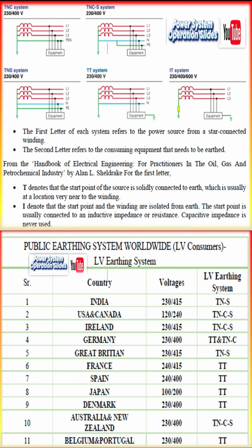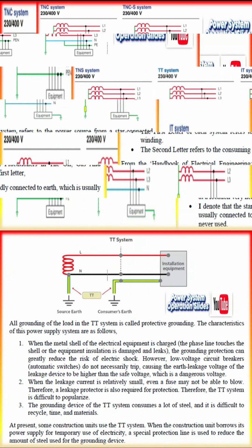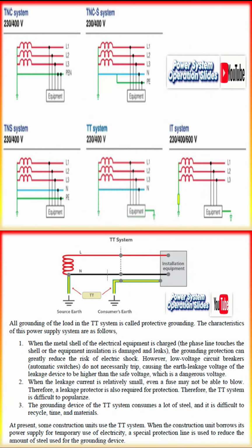In this sort of earthing system, the connection to the supply source is connected directly to the earth, and the load end or installation metalwork is also directly connected. As a result, in the case of an overhead line, the earth's mass will serve as the line's return path. Because the power distributor only offers the supply neutral or protective conductor for the connection to the consumer, the neutral and earthing conductors must be separated during the installation.